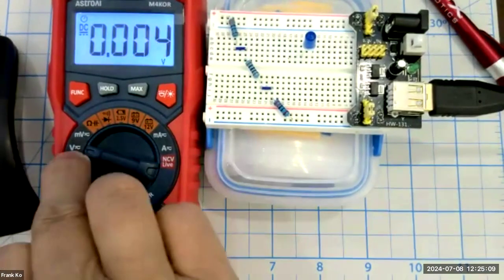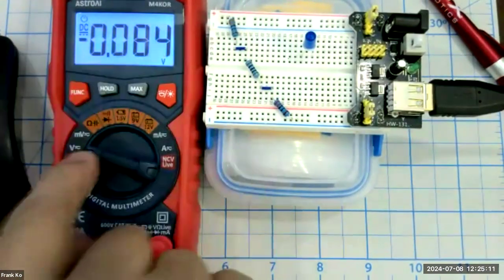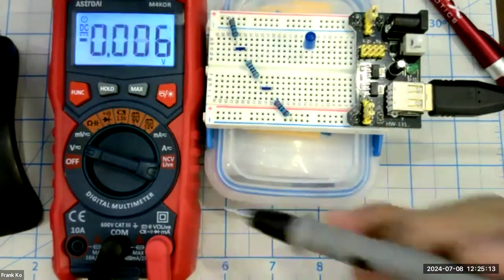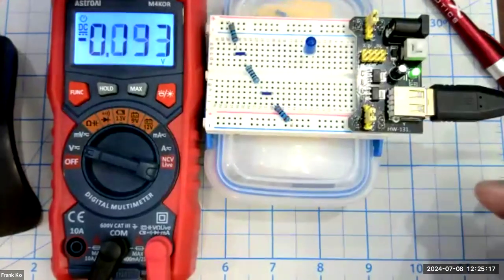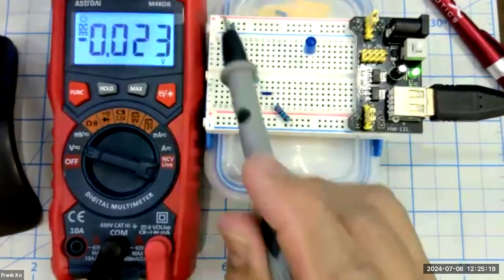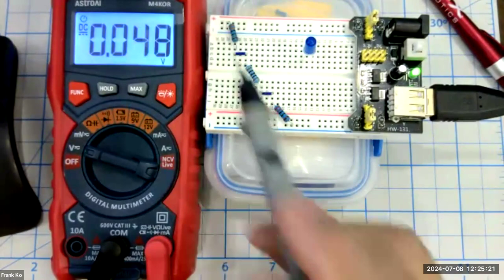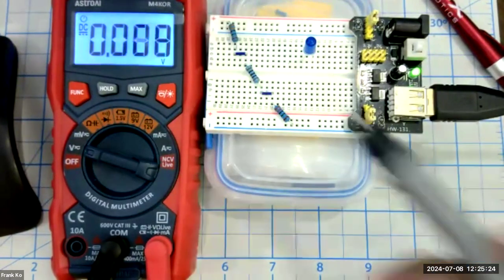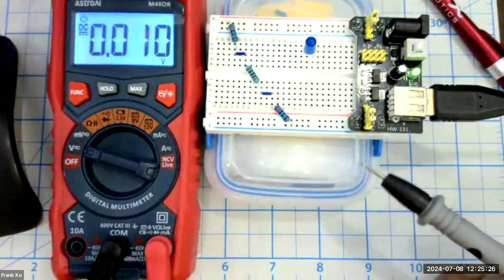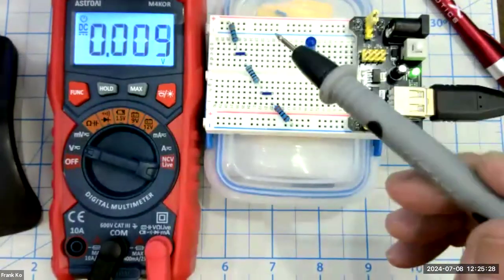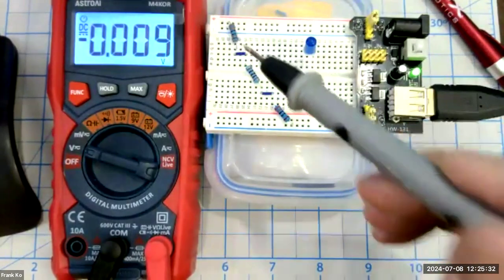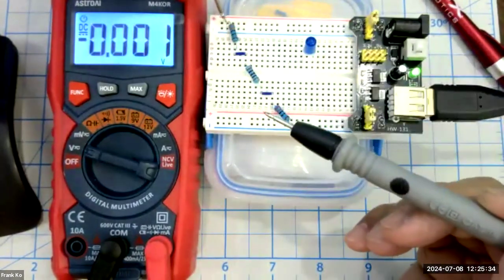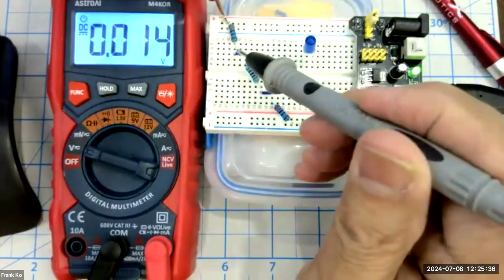Okay, set this back to DC volts. It says DC voltage. And let's go ahead and put our probes across. I'll turn this guy on, might be helpful. There we go. Now it's on. My jumper is back in place of the LED. Presumably current's flowing. Presumably I have voltage across each of these resistors. Each of these is dividing that total of 5 volts into parts of the circuit. So here we expected something close to 2.54.